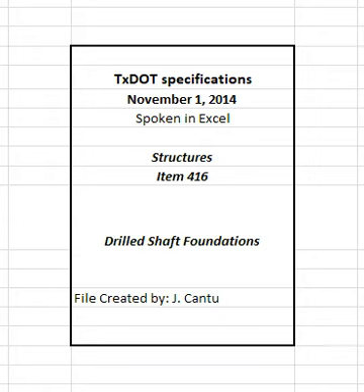Payment for the portion of individual completed shaft length in excess of 5 feet and up to and including 15 feet more than the maximum plan length shaft, as defined in this item, will be made at a unit price equal to 115% of the unit price bid per foot of the specified diameter. Payment for the portion of individual completed shaft length in excess of 15 feet more than the maximum plan length shaft, as defined in section 416.5.1.2, maximum plan length shaft, will be made at a unit price equal to 125% of the unit price bid per foot of the specified diameter.